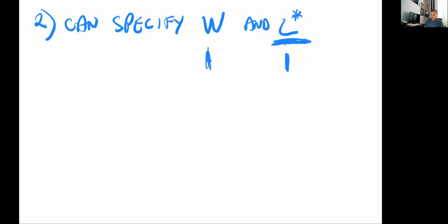So since I want to, and this is point number 3, since I want to get rid of resistors, which I really use for biasing circuits, okay? We, instead of resistors, are going to be using current sources to bias. And so you can imagine, to get rid of one resistor, I'm going to be designing a current source with several transistors, and that's great because we know how to make them. They're cheap.